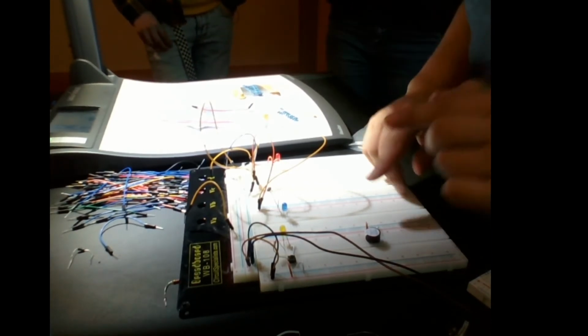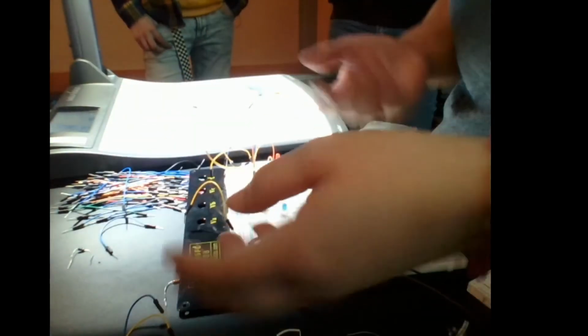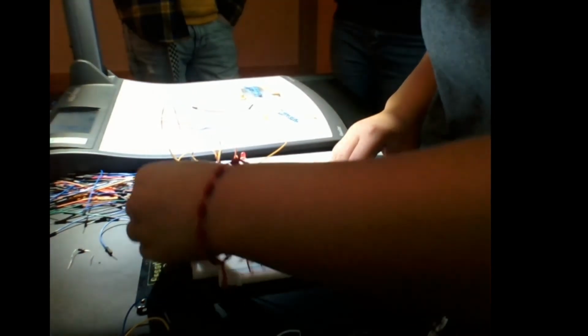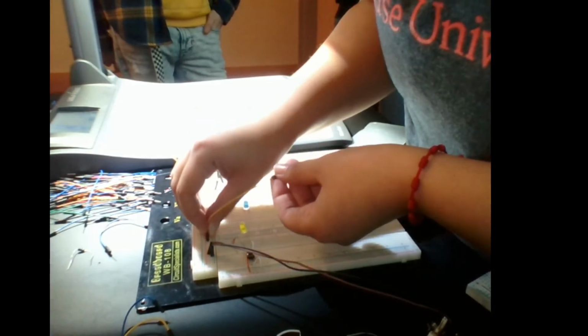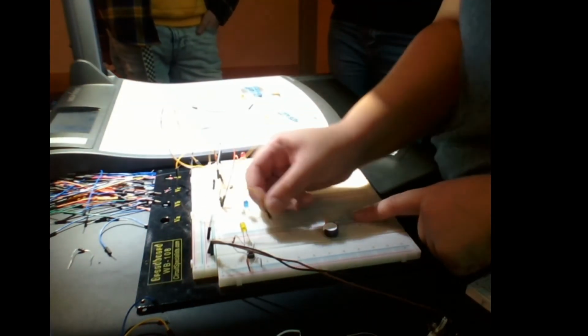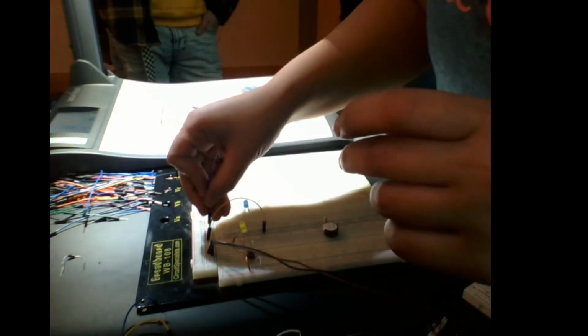But let's turn off our power supply. Let's disconnect these because we're no longer using the button. So we have this power going to here. That's fine, we don't need to move those. And I'm just going to put our positive to now this rail because that's where it's connected here, if you see. So I'm going to move it to this power rail. And then make sure you always have ground or else your circuit's not going to work.